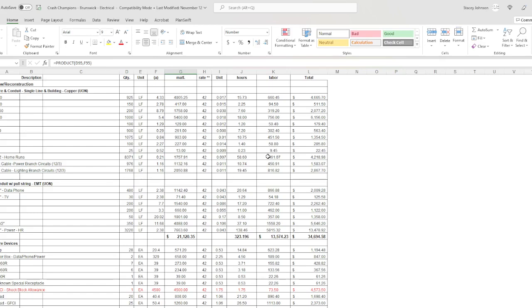It tells them everything they need to know, and if they know their trade, which they do, they can determine if the numbers you're giving them are crazy or overboard. Number 12 wire, you're going to always have a lot more of that, because most of the power components run with 3 number 12s. So you'll run one length for the conduit, but you have to multiply that by 3 for the home runs.